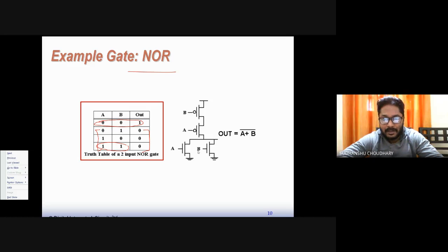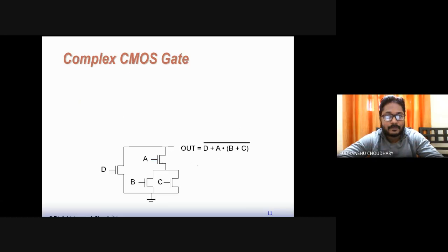Again, you will notice here that when these two MOSFETs, that is both NMOSes, are on, then the output node can be quickly discharged, okay, compared to only the case when one MOSFET is on. So that means delay in this case will be smallest, TPHL will be smallest in comparison to TPHL in these two cases. Okay. So this one has to remember.